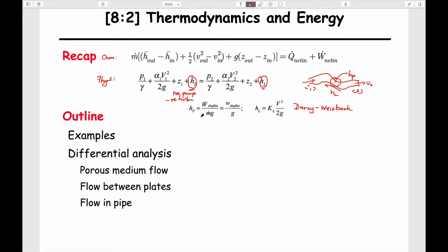And gravitational acceleration. And again, the units of this should work out to the right magnitude. We can look at it as a power per unit mass flow rate, I guess this would be. It can be a loss or an input into the system, but this is really what you want. When you say a pump has 20 kilowatts or 50 horsepower, then W dot is what we're talking about. Uppercase W dot is the power. So those are the units and the behavior for the physical exposition of this equation.